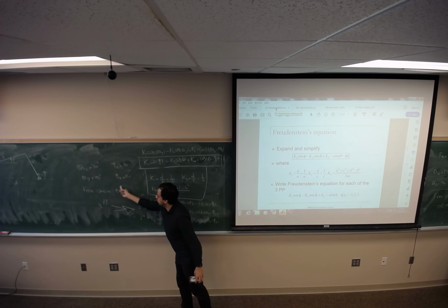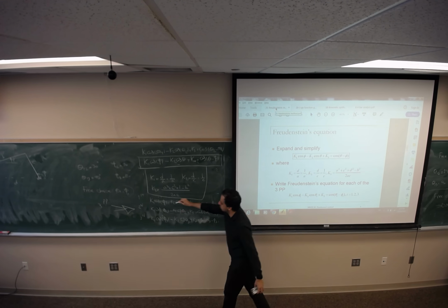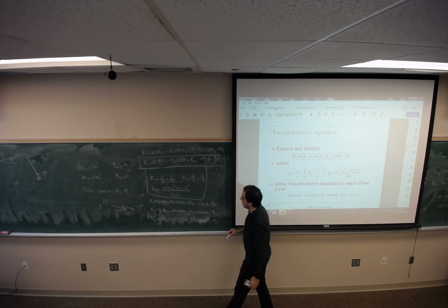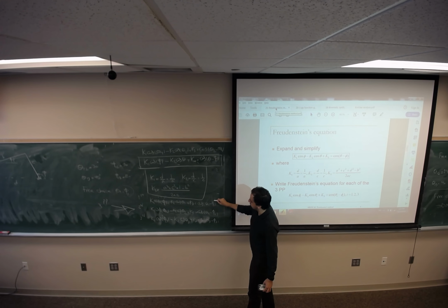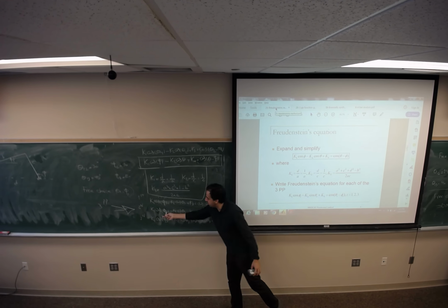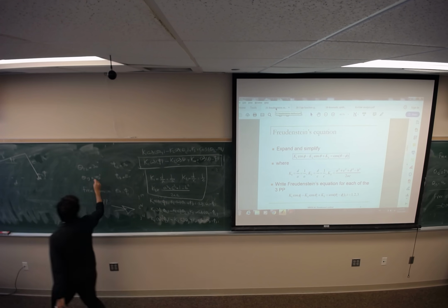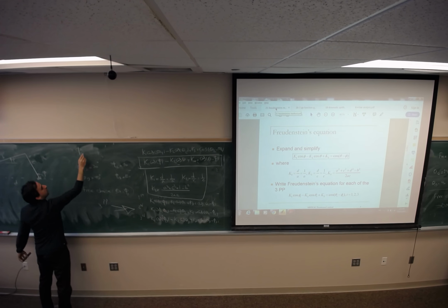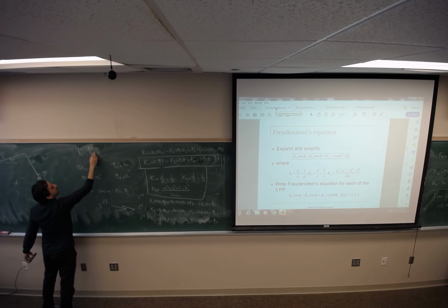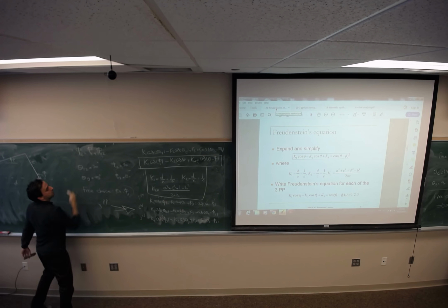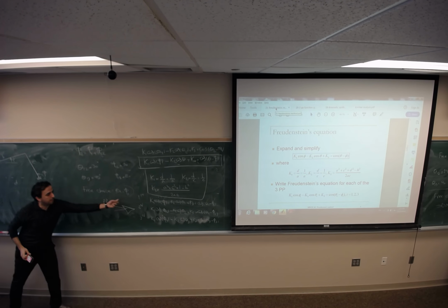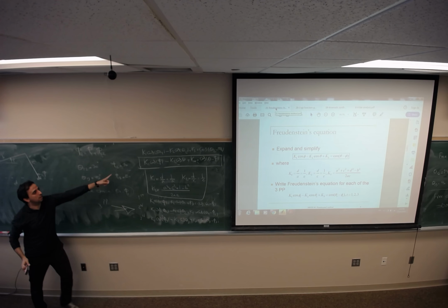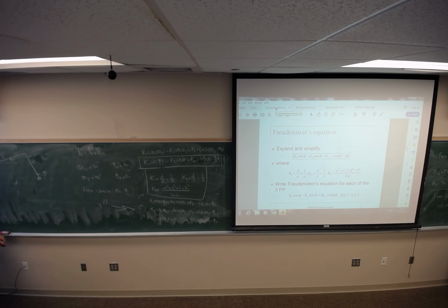You pick them as free choices. So these 2 are not known, but theta 1 minus phi1 is known. What would be phi2? Look at this. Phi2 is phi1 plus phi12. Whatever you pick for phi1, just add it to the given data, and you will get phi2.